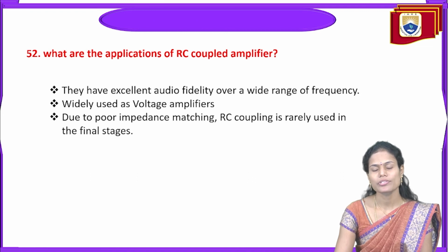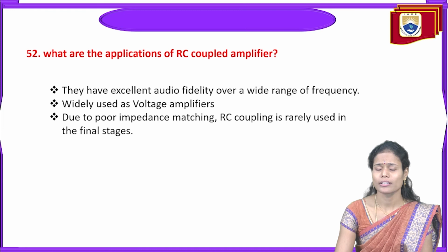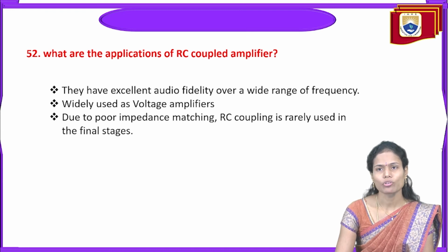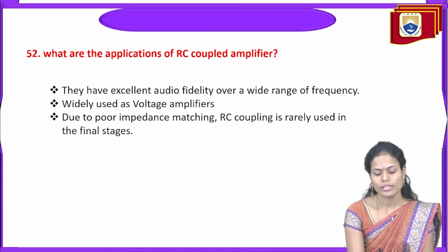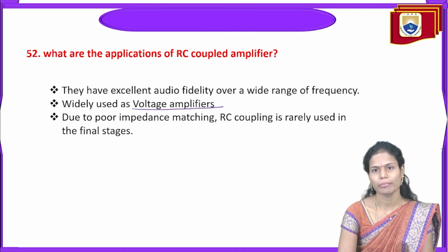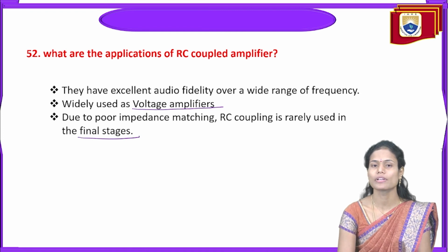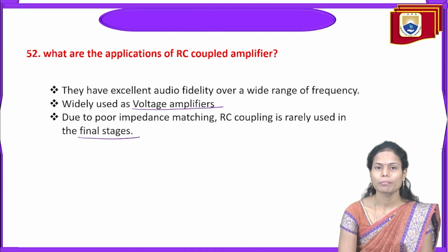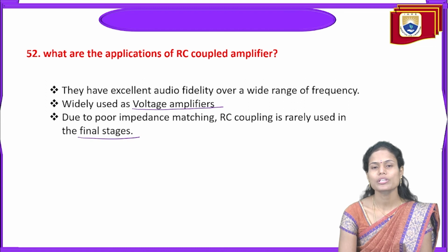And what are the applications of RC coupled amplifier? They are able to provide excellent audio fidelity over a wide range of frequencies. In most cases we utilize them for voltage amplification, and due to poor impedance matching, RC coupling is rarely used in final stages. In most cases we will not utilize RC coupling in the final stage. Mostly we prefer transformer coupling in the final stage to provide the impedance match.